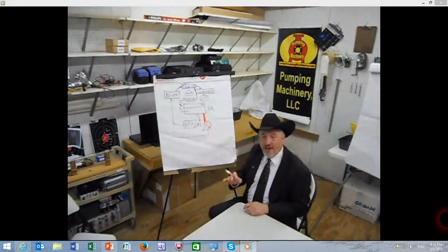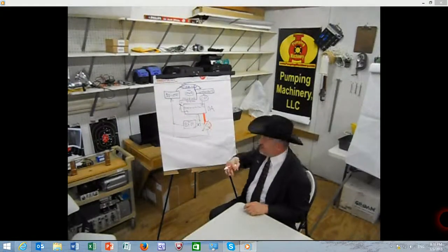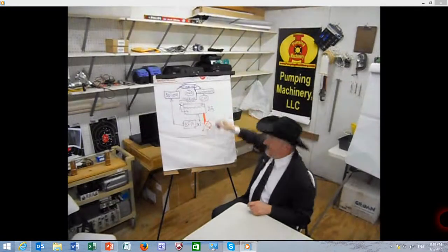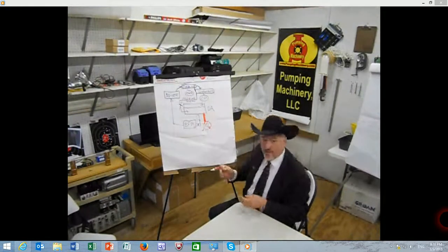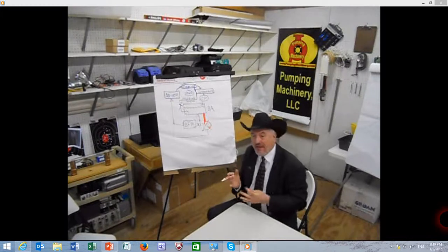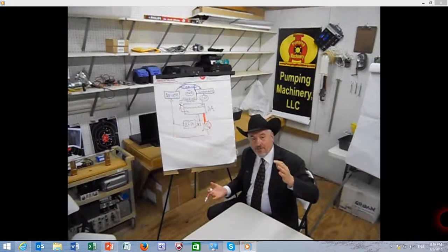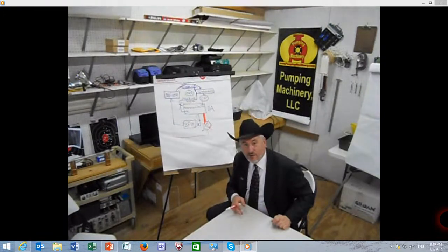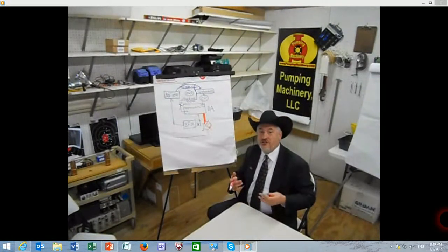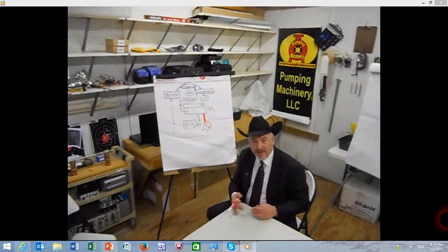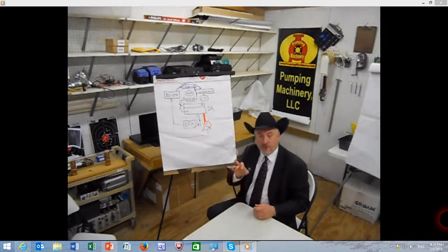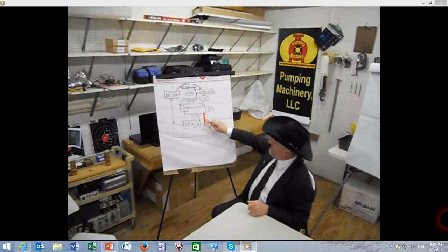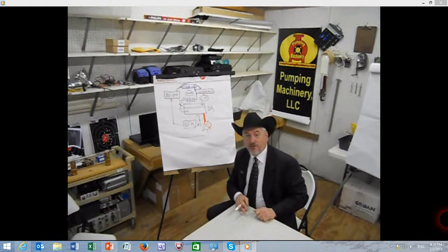But the pump number 1, the non-running pump, is now experiencing lower pressure on top of the surface of the DA, but higher temperature. If this pipe is well insulated, it retains, imagine 100 feet of pipe, 16, 18 inches diameter, it has a lot of water, maybe 1,000 gallons of water or so. All this water is now at lower pressure, and if you go low enough, it can become lower than vapor pressure at that elevated temperature.